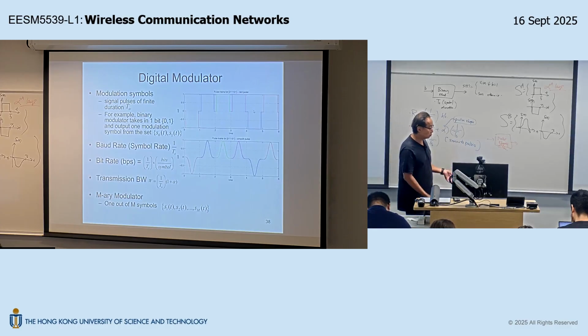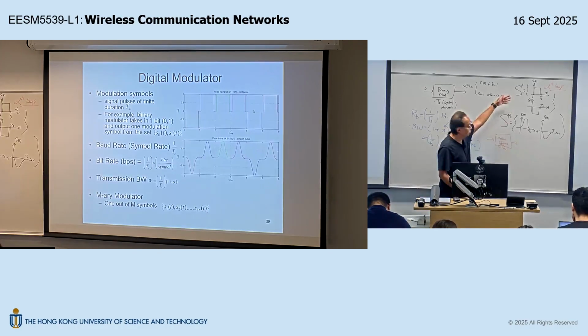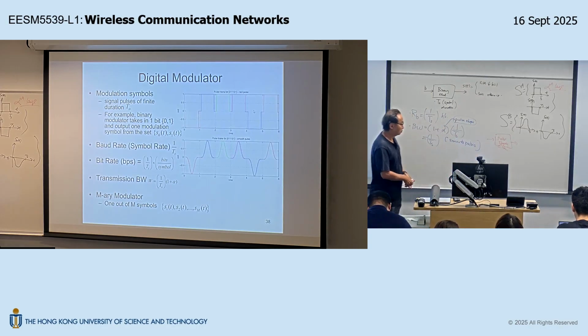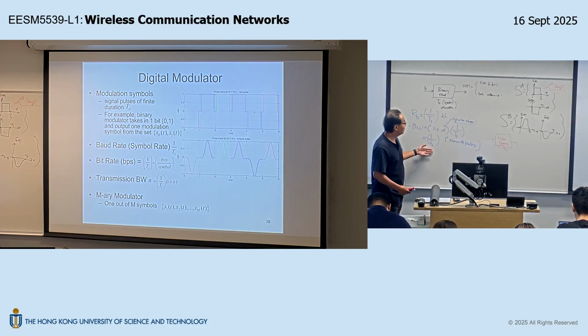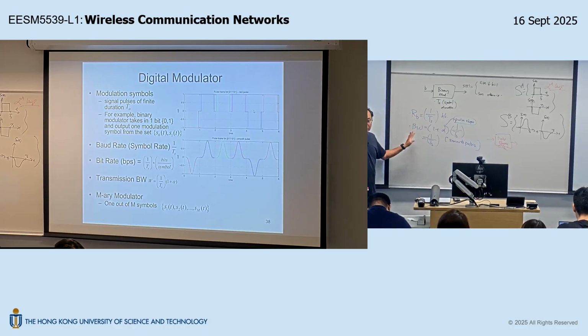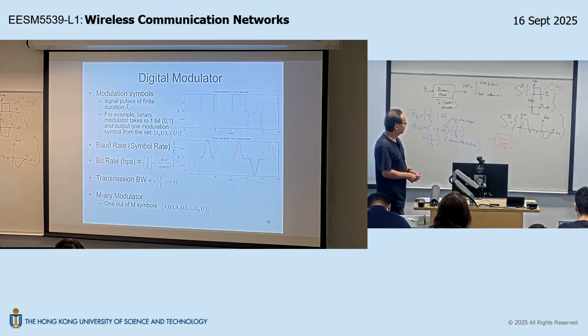So usually, even if your original design is not smooth, before you transmit onto the radio channel, you always have a pulse shaping filter to smooth out the pulse. So we just assume you have a smooth pulse design in your signal set design so that the bandwidth will be given by this. Is that okay? So with this, you can see clearly this is a trade-off. If I double my bandwidth, I will double my bit rate. So that's the fair trade-off.